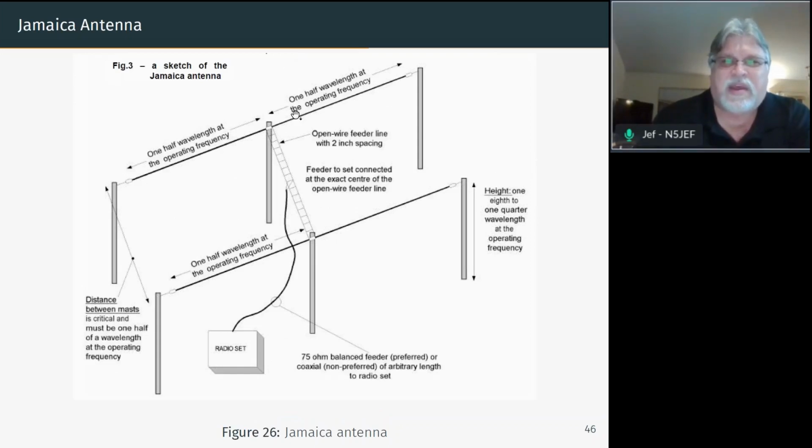Here's the same idea, but instead of a half-wave dipole, they're using a full wave. And so they get about 3 dB greater than a half wave. They're using 2 of them phased, so that's about 6 dB total compared to a dipole. The problem with using full wave dipoles, they work fine. They're just really hard to match with the impedance, because just like operating an NFED half wave, this is 2 NFED half waves, and they're very high impedance, so matching can be a problem.